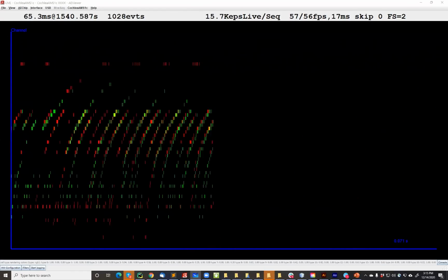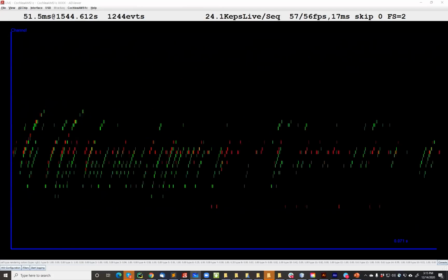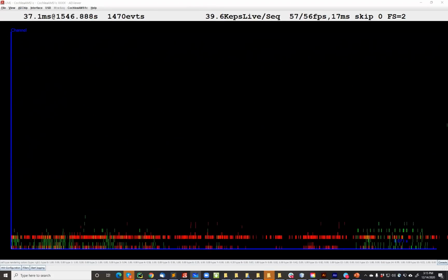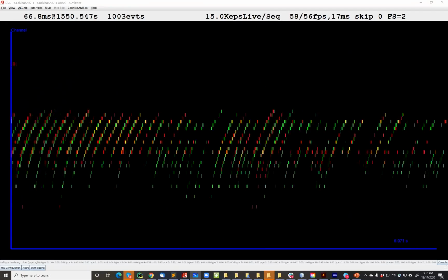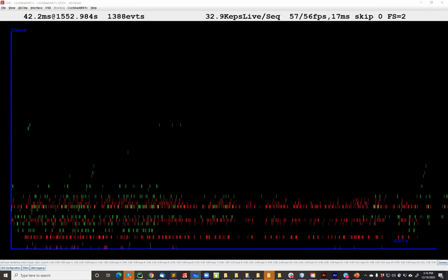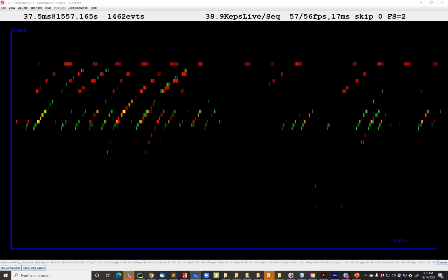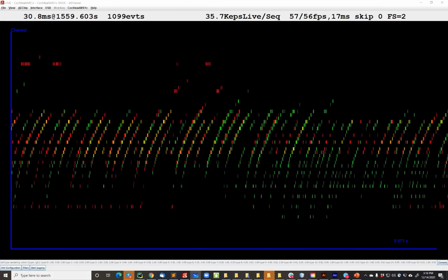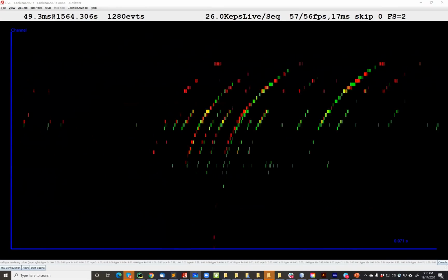And because it's a cascaded architecture, the output of every subsequent cochlea stage is going to be much sharper, like an additional 40 dB per decade sharper than the output of the previous stage. That's how you can get this really sharp roll-off as you go down this cascade. So the output of the cochlea that you're looking at is a cascaded filter bank architecture. It's not a parallel filter bank architecture.